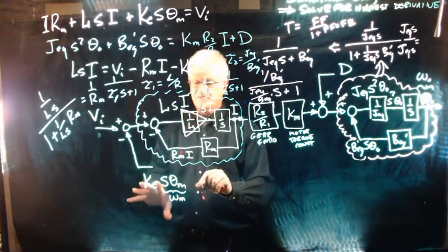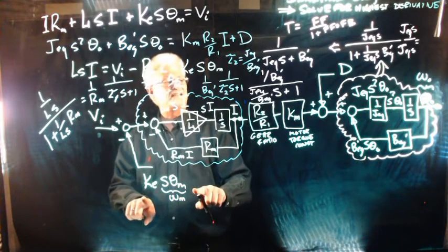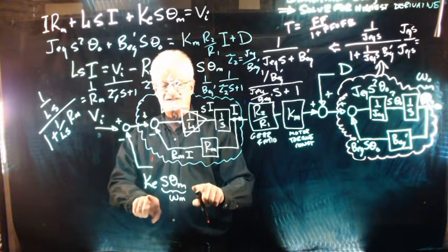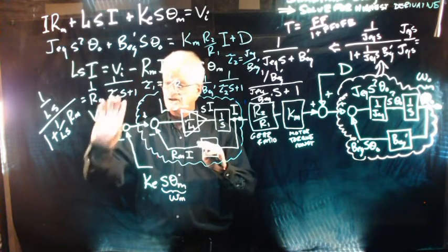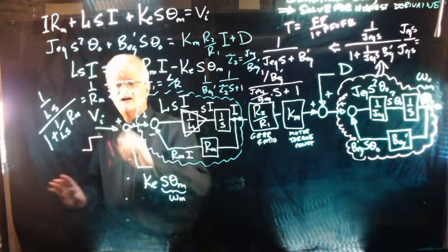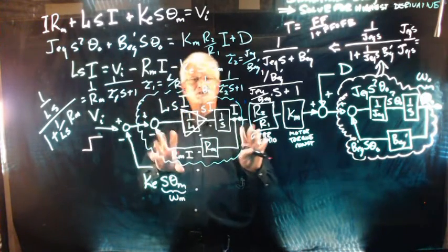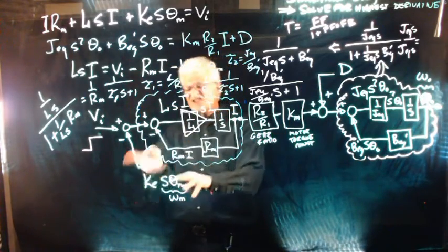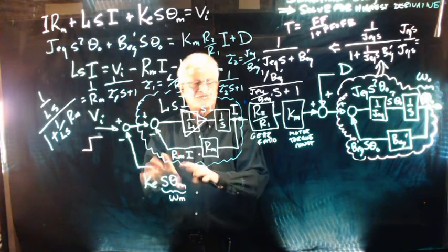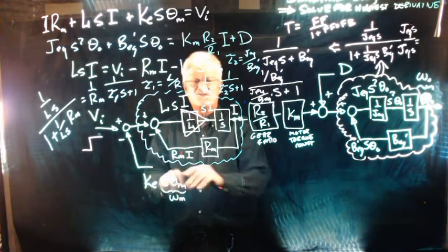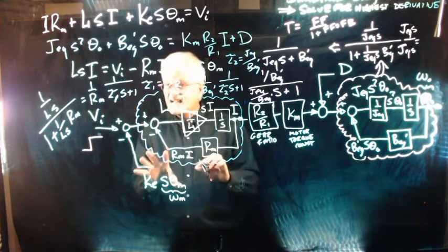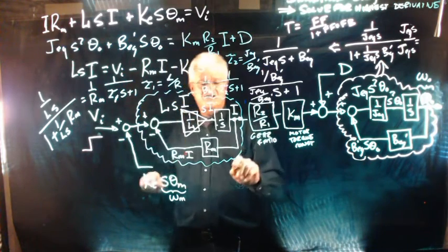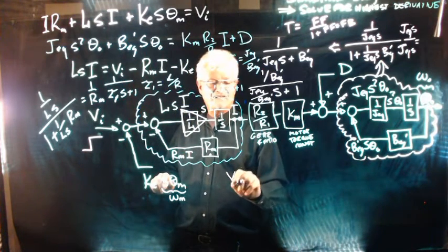The first thing is I'm going to pretend that the motor speed is 0. So it's at 0, and we're going to apply a step input of the voltage. The motor speed is 0, and then we're going to look close at what happens to the speed and the current. For this point in time, I'm going to more or less neglect the motor speed. It's not exactly neglectable, but I'm going to do it anyway for the sake of illustration. So we have Vn coming in here.